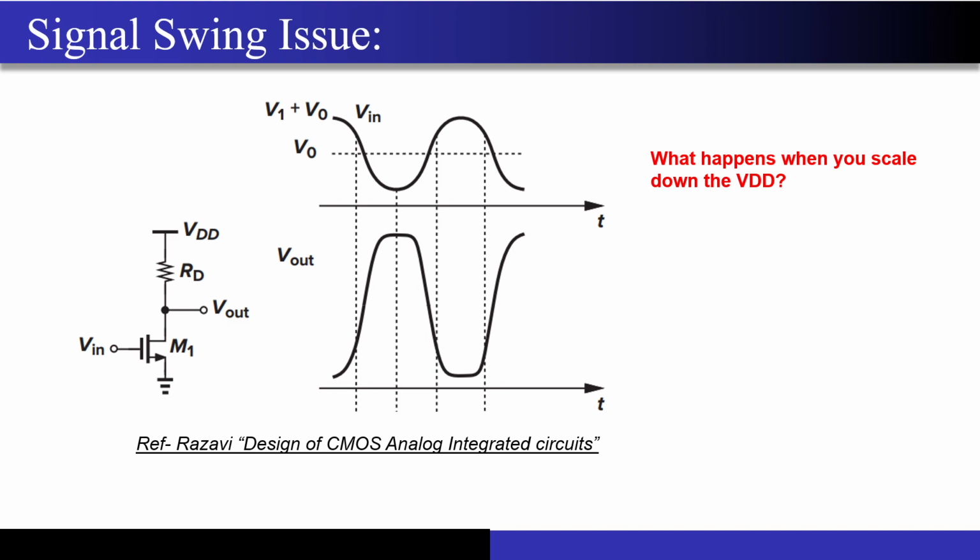No. I'm saying in the aspect ratio, the W/L, that L is the channel length, right? That channel length is completely in your control. See, the technology node is the minimum channel length that you can have for that particular technology node. So it doesn't mean that if I use the 3 nanometer technology node, I can't have devices with a channel length of 180 nanometer as well. It just tells you the minimum channel length that the foundry can give you for that technology node. Oh, okay. I get it.